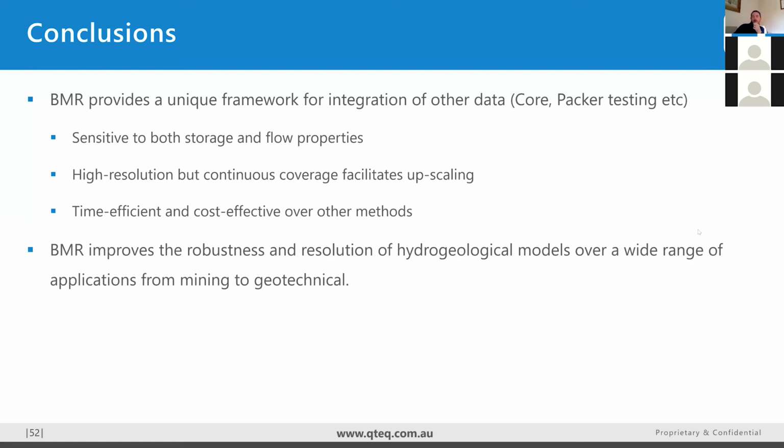So it can help in a couple of different ways, the data. You can use it to quickly determine what your salinities are going to be to help decide on treatment of your extracted water for a pump test, or you can just use it to help potentially replace that pump test as well.